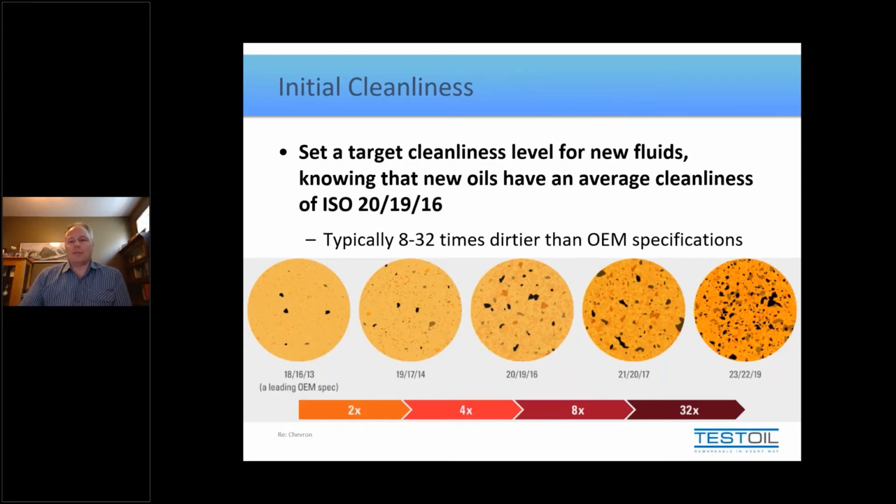Now, like I said, people have two schools of thought when it comes to hearing this. One is that it's not clean enough, and now you understand maybe why. The other school of thought is, why are they leaving it up to me? Why are they leaving it up to my system filtration to do this? It's because, generally speaking, your system filtration should be capable of handling it and bringing it within check in a short period of time, and this isn't considered to be much of a burden. So it's not to say it's the end of the world and that nobody's doing things right, but we just need to realize that every time we add new oil, we're adding in oil that is likely more contaminated than the oil that's already there.